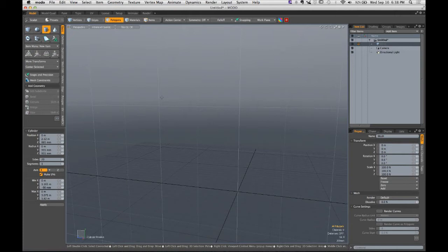With the cylinder tool active, single left click inside your OpenGL viewport. Just single left click. You can see that the computer's drawn some move handles. That's step number 1. Step number 2, move your cursor away from these move handles. Move it away. And look, I'm moving mine pretty far off over in here, okay? Step number 3, hold the control key down on your keyboard. Step number 4, drag to the left or right, and a circle will be born.